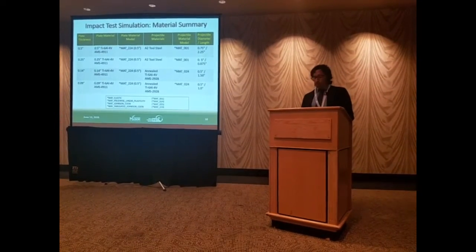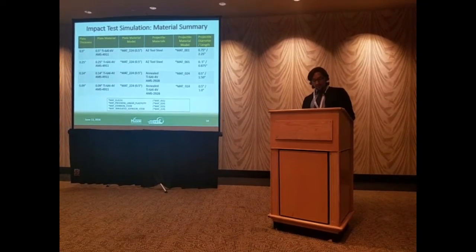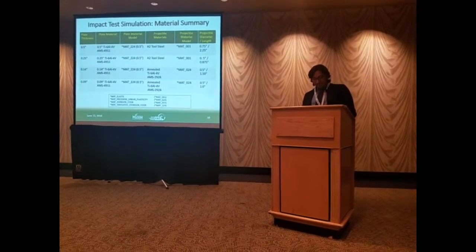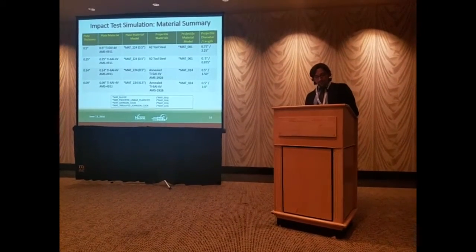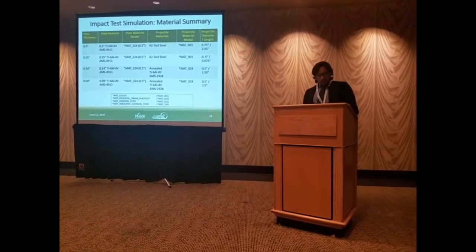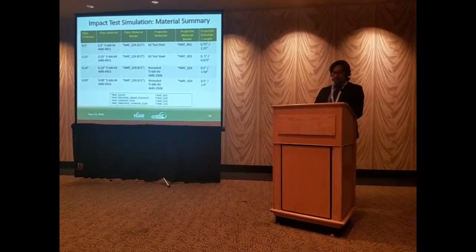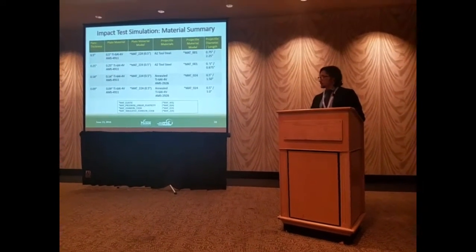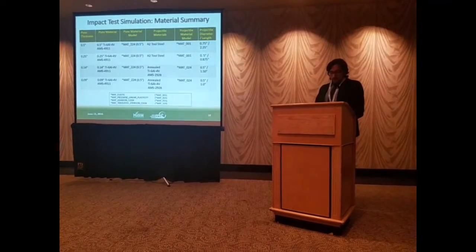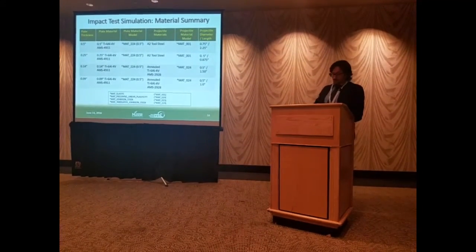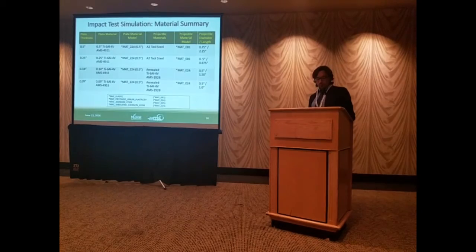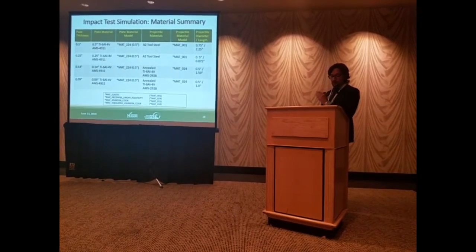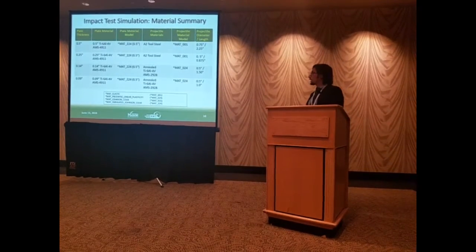Instead, for the 0.14 inch plate and 0.09 inch plate, the material of the projectile used was annealed titanium, and the plastic deformation is not negligible anymore. And so we use MAT piecewise linear plasticity, and we get the material property from literature. Instead, for the plate material, it doesn't matter what the thickness is, because we always use MAT224 developed from the half-inch plate.